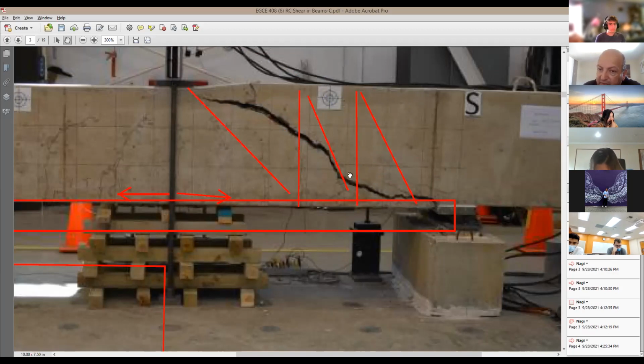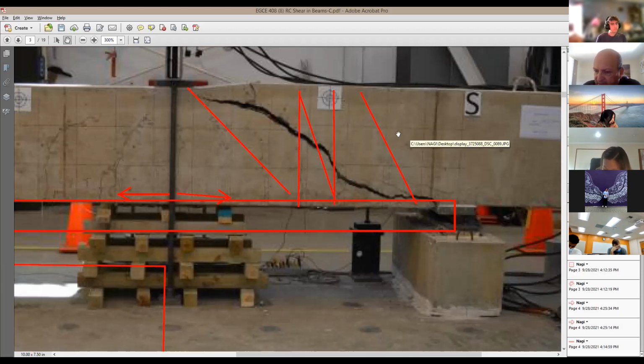Now we have the strength coming from these 2 vertical ties. And this crack needs to be at 45 degrees. So here I'm violating this rule. It's going to go at 45 degrees like this, but guess what's going to happen? It's going to have this rebar in the middle, holding the beam together. If I keep the spacing between the rebars equal to 1/2 of the depth, there is no way that this is going to be at 45 degrees. It's going to be like 30-something degrees, a ratio of 1 to 2, correct?